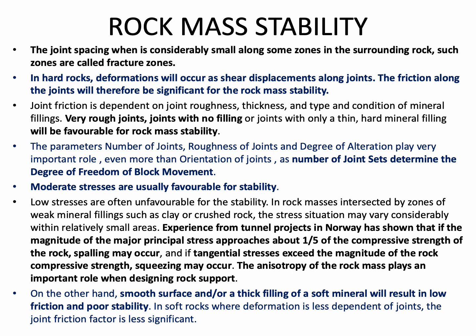On the other hand, a smooth surface and or a thick filling of a soft mineral will result in low friction and poor stability. In soft rocks, where deformation is less dependent on joints, the joint friction factor is less significant.